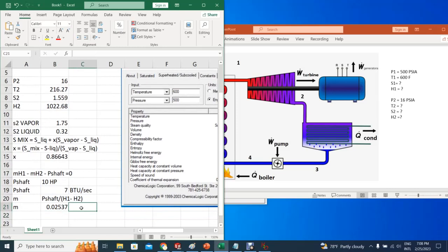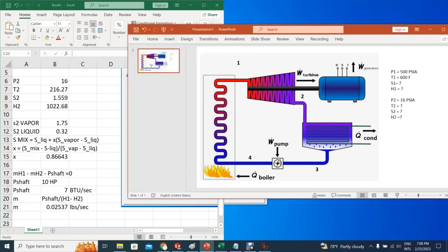That would be BTU, that would be pounds per second. That's flow, mass flow. Excellent. Now that's the amount of mass that I need per second to go through the whole system. It could be a little bit more because I'm assuming the expansion engine is adiabatic reversible, which it is not. It has some efficiency, maybe about 70% or so, the turbine.